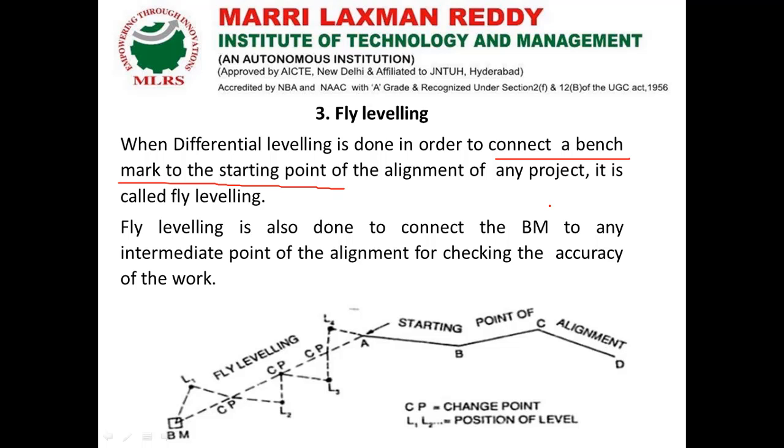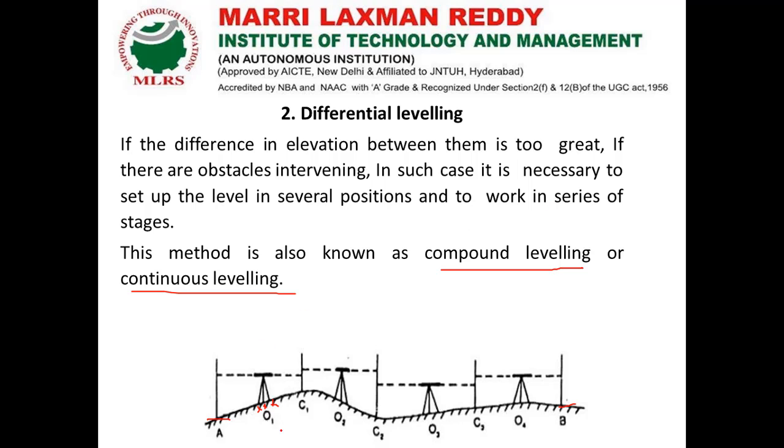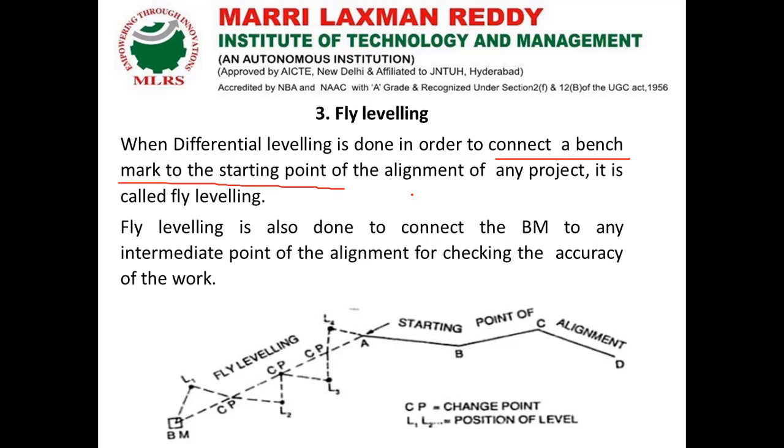In the previous differential leveling, we found the level difference between points A and B with the help of continuous leveling, but in fly leveling the reading is connected from the benchmark to the starting point of the project, done continuously.